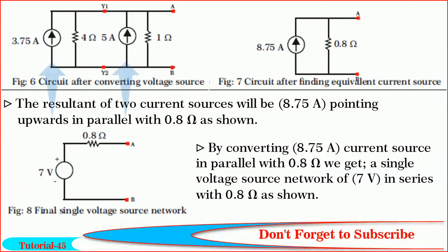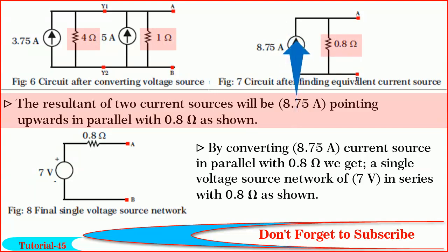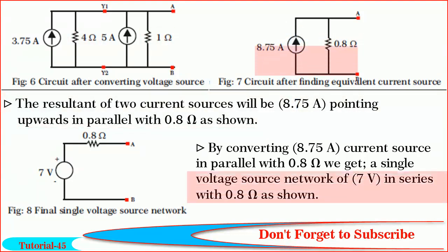Now, we get two current sources in parallel. Hence, by finding their equivalent, we get 3.75 ampere plus 5 ampere equal to 8.75 ampere in parallel with 4 parallel 1 equal to 0.8 ohm. Finally, by converting the current source, we get 8.75 ampere into 0.8 ohm equal to 7 volts in series with 0.8 ohm as shown in the figure.